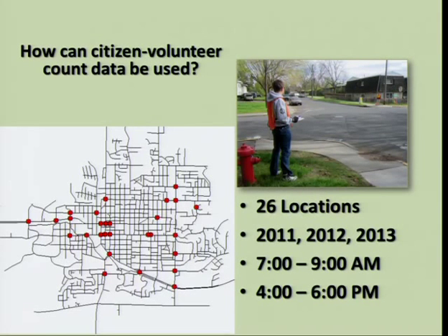Any other thoughts? Yeah, you could use it as a basis, like on a multi-use trail, for looking at needs for a bicycle signal, at least as a starting point. Yeah, and so I think in the end, these are great for starting points. You know, begin to say, all right, there's high traffic here. I've heard one person say, oh, we're going to use those for traffic signal timing. Nah, I don't think so. 2 hours, that's not going to be enough data. But maybe it's a start to say, now let's go back and do a more thorough study of that particular intersection so that we can do something like a safety analysis or traffic signal timing.